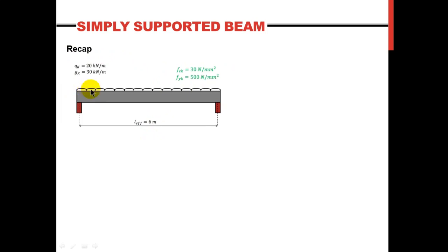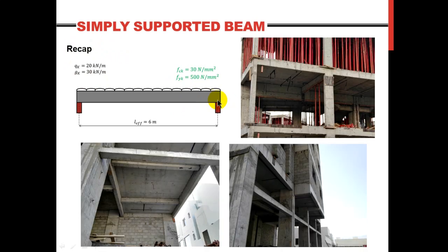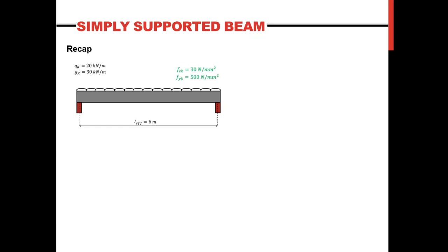Of course, the loads on the beam must be given as well, so that you can determine the ultimate moment on the beam for the bending design, and the maximum shear force for the shear links design. Now, we said that the simplest beams can also be seen in RC structures. But when we talk about rectangular sections, they might not appear as often when compared to L and T beams. And this is due to the fact that we always have the monolithic pouring of concrete.